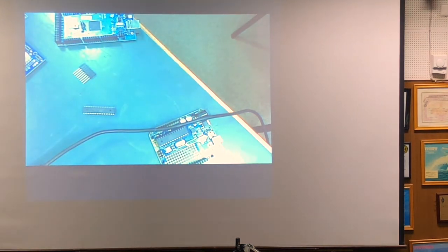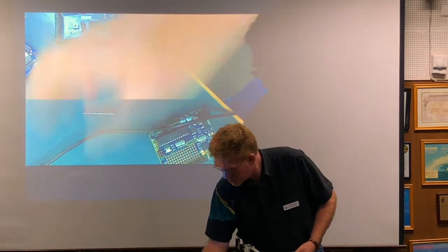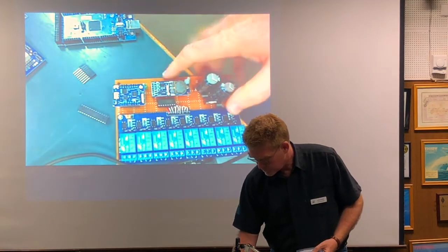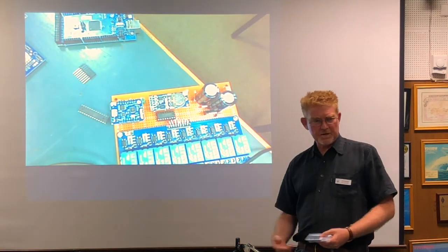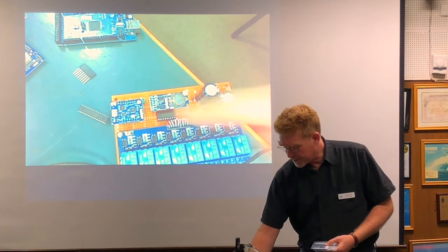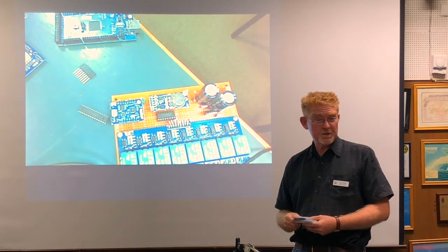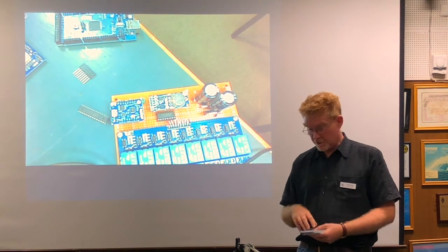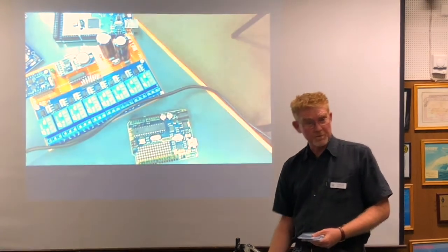Thank you. Have you got much in the way of the Internet of Things, like shields for Arduinos? The chip I showed you here, there's a range of these chips called ESP modules, ESP-12, 12Es, 12Fs. That's one way of packaging. Another way is a little tin box. There are Arduino shields with those tin boxes already on them, so you can use this kind of Arduino to drive one of those modules.